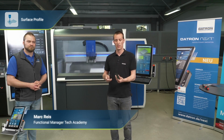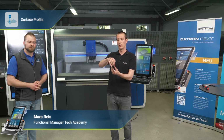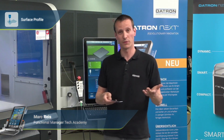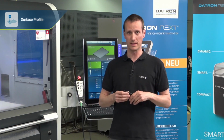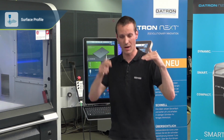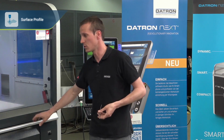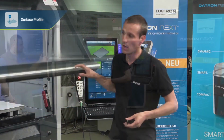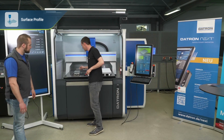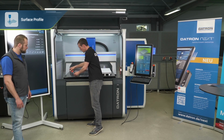The surface profile is like doing a lot of probing points over the surface of the part and then compensating the z-axis. Very good for housings where you have a little bit of deflection from the process before that is just not perfectly even. That's where you can use the 3D probe to compensate this. And I'm bringing this part now into my centric vise.